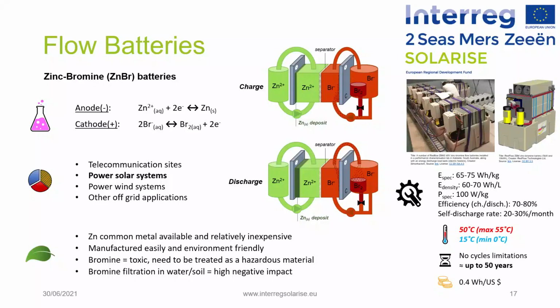The disadvantages include the need to be fully discharged every few days to avoid zinc dendrite that can puncture the separator, the need every 1 or 4 cycles to short the terminals on a low impedance shunt while running the electrolyte pump in order to completely remove zinc from the battery plates. And finally, low power density during charging and discharging, resulting in high energy cost.